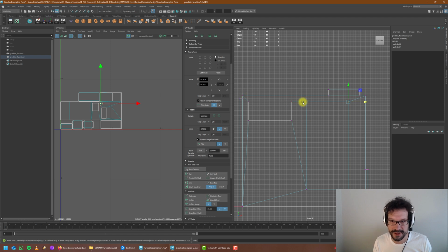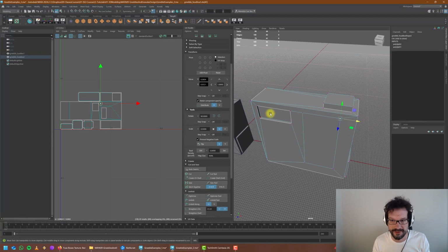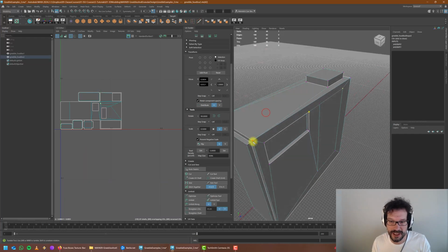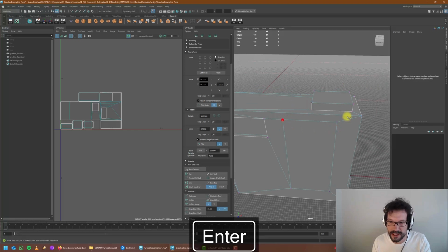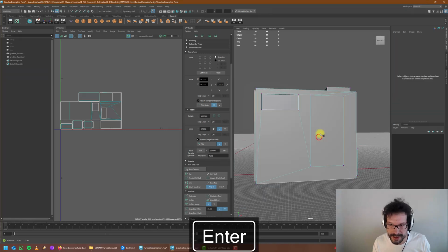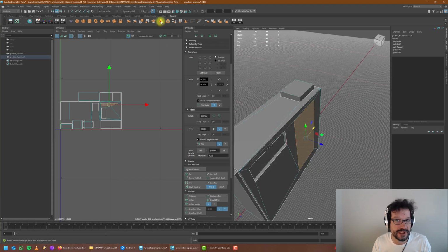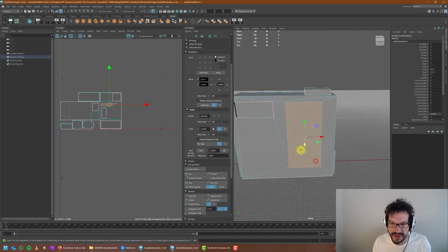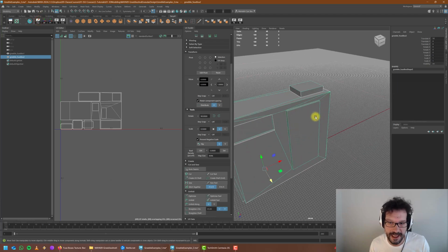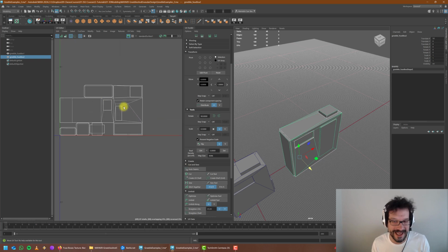Always check the alignment as well. As you can see, the alignment of the vertices is not good. Right now this is not a quad, or even though it looks like a quad, it is not a quad. So I'm going to break apart the edge flow in here to make sure that everything flows to an appropriate vertex. So everything turns into either triangles or quads in this case. Okay, this is good and all. So let's grab this face and simply, I don't know, extrude it just 1 centimeter, and that's it. You can do that. Now this object has obviously differed in its UV map design, so let's fix that.